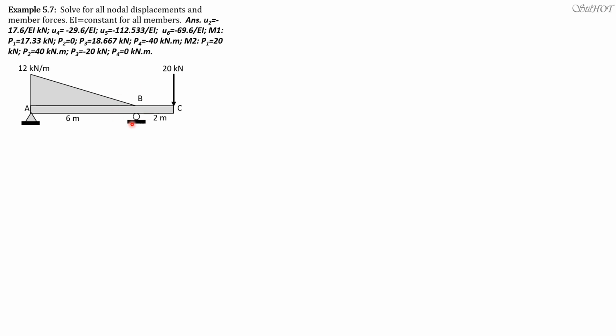So in order to have nodal loads at B, or at 2, we need the fixed force or fixed moment reaction, and fixed force also at B. And we have here 40 kilonewton. Since the loading on AB is triangular, we have a formula for that available.